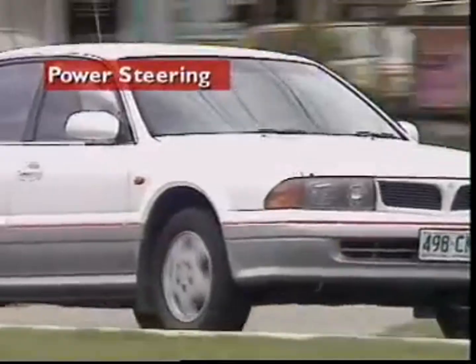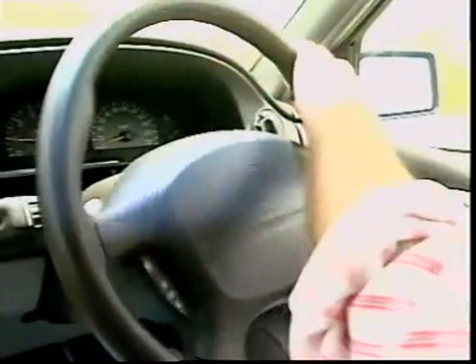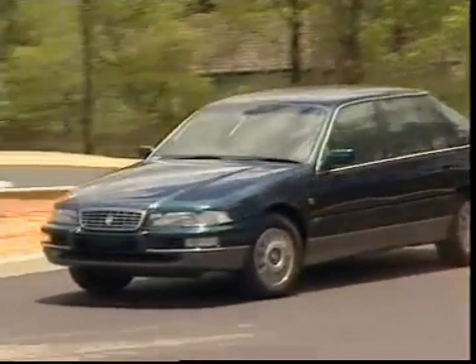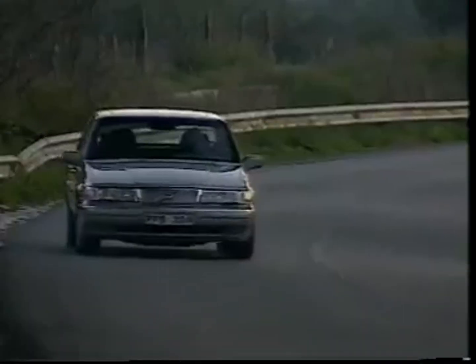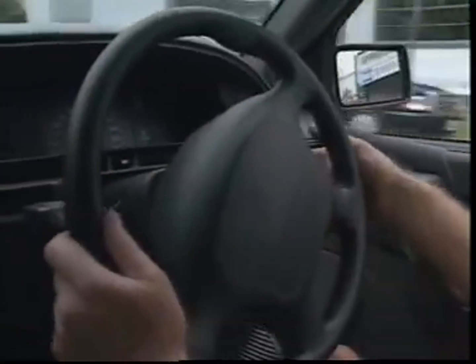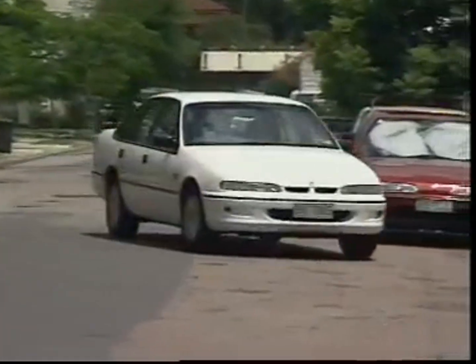This section examines power steering. Increased applications of front-wheel drive and wider low-profile tyres places additional loads on front wheels. Steering then demands more effort from the driver. Power steering helps to reduce the additional effort needed. It's of most benefit during slow cornering and when parking. Assistance is provided as soon as the steering wheel is rotated in either direction, and is designed so that even if system failure occurs, the vehicle can still be steered.